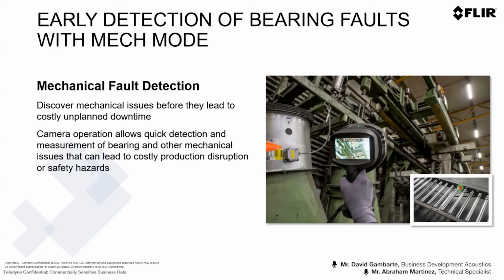And now, just to point out, this is a non-invasive system. So basically, you don't need to put any sensors anywhere. You just walk with the camera along your premises and find where the mechanical faults are. Of course, after this, you get the kurtosis, crest factor, and the sound pressure level in decibels, and you make your own analysis, doing an inspection in the components where you have mechanical faults.